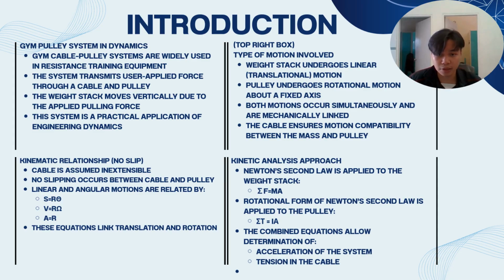This project analyzes a gym cable pulley mechanism commonly used in resistance training. The weight stack moves vertically while the pulley rotates about a fixed axis. Because the cable does not slip, linear and angular motions are linked using kinematic relationships. Newton's second law is applied in both translation and rotation to analyze the system dynamics.